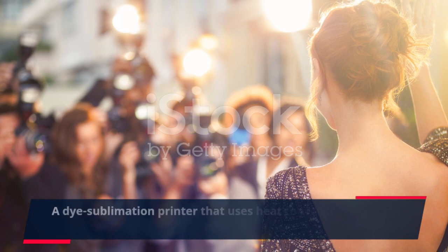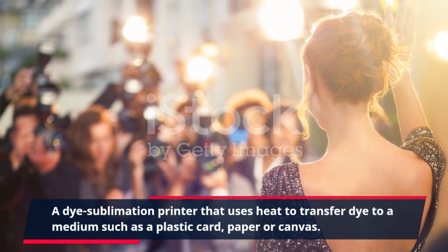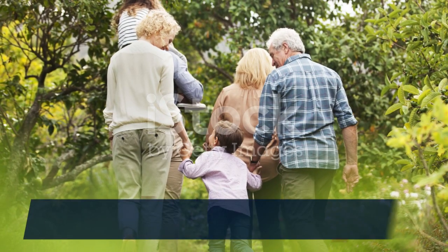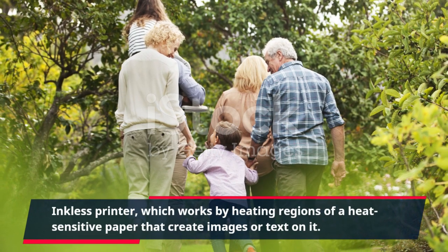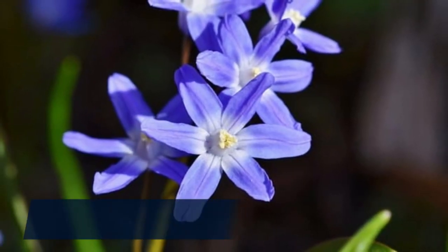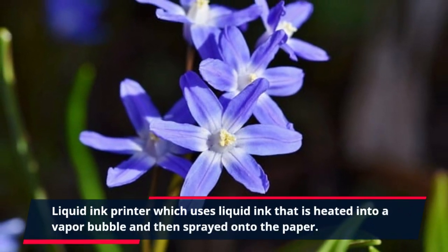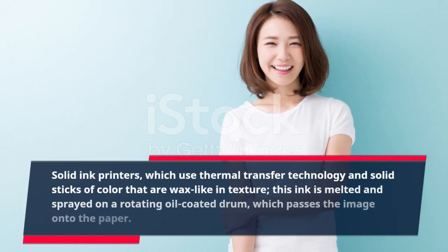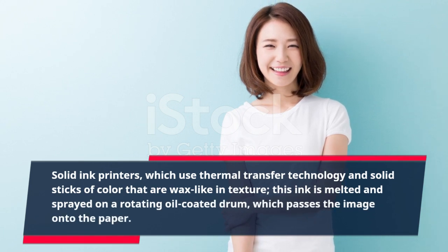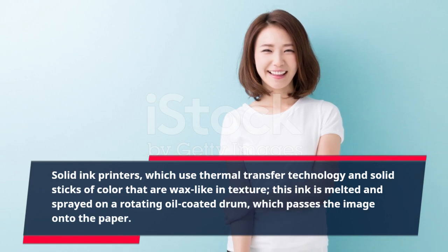A dye sublimation printer uses heat to transfer dye to a medium such as a plastic card, paper or canvas. Inkless printer, which works by heating regions of a heat-sensitive paper that create images or text on it. Liquid ink printer, which uses liquid ink that is heated into a vapor bubble and then sprayed onto the paper. Solid ink printers, which use thermal transfer technology and solid sticks of color that are wax-like in texture. This ink is melted and sprayed on a rotating oil-coated drum, which passes the image onto the paper.